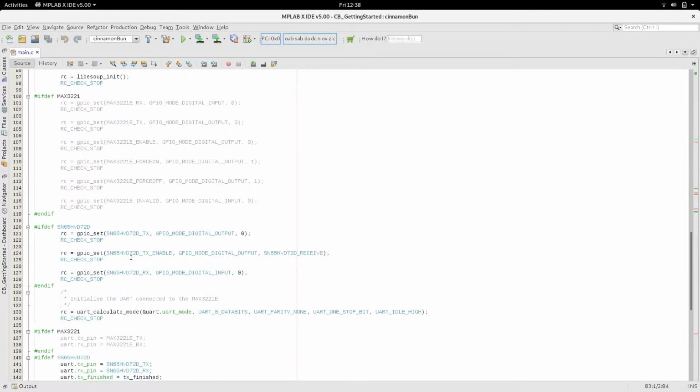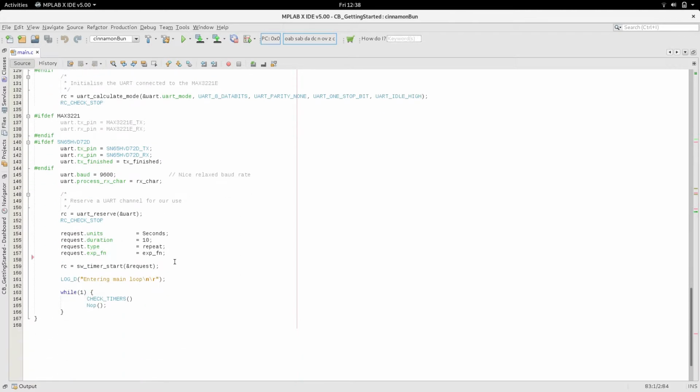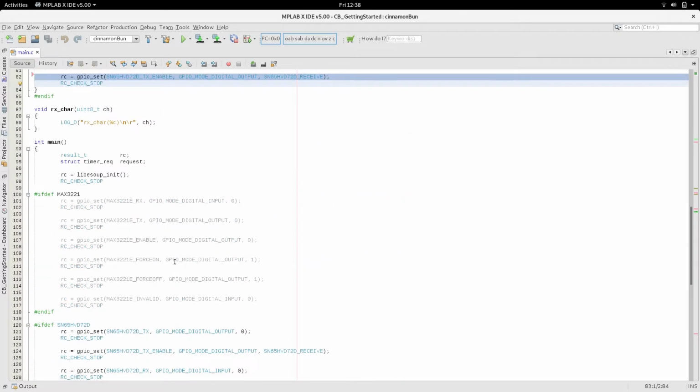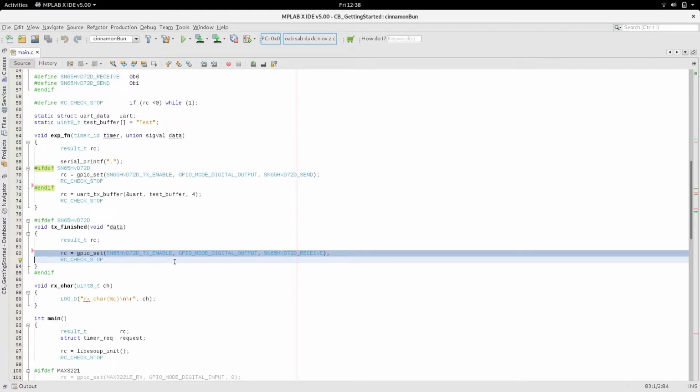And I'll commit this code later today, hopefully, but it's more or less exactly the same, except that we now have to tell the transceiver to go into transmit or receive mode, and we have to know when the transmitter's finished to do that, so we use the callback.